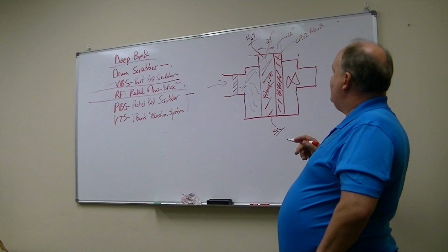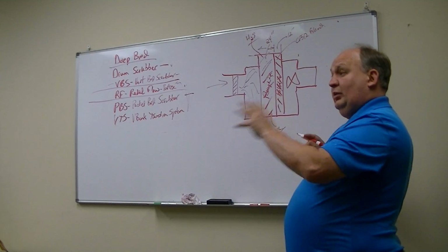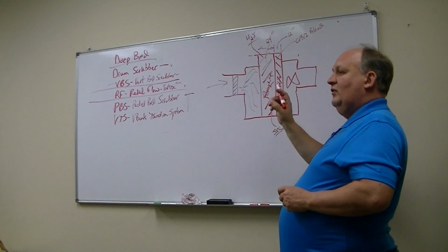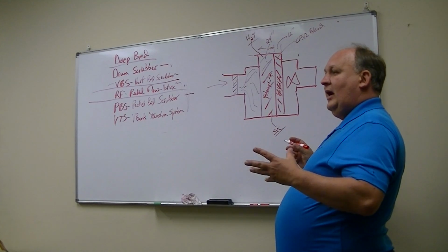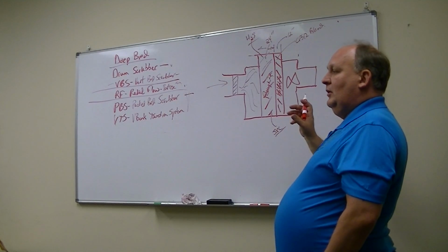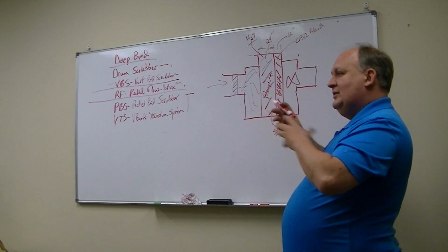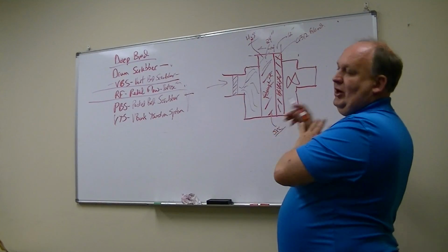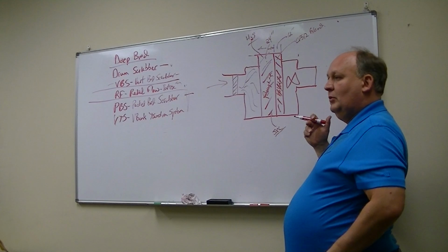That CPS 12 blend is a blend of plain activated carbon and 12% Pure Air 12 media, which is 12% permanganate on aluminum, okay? So the two medias combined is kind of a shotgun effect, right? Just capture everything else that comes through, all right?